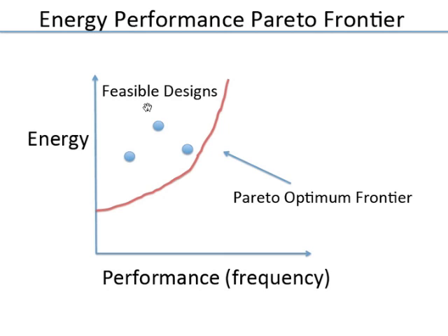As a designer, you have choices at all levels of the design hierarchy. Architecture, for example what kind of memory I'm using, caches, etc. Microarchitecture could be how many pipeline stages, how many things running in parallel, do I have a hardware engine. Sizing is another choice, what kind of sizes do I use. And now we are also talking about voltage as a choice. Threshold voltage could be another. So you have so many design parameters, and all these design variables you can vary, and for every possible value you get a particular design which has a certain energy and certain performance.